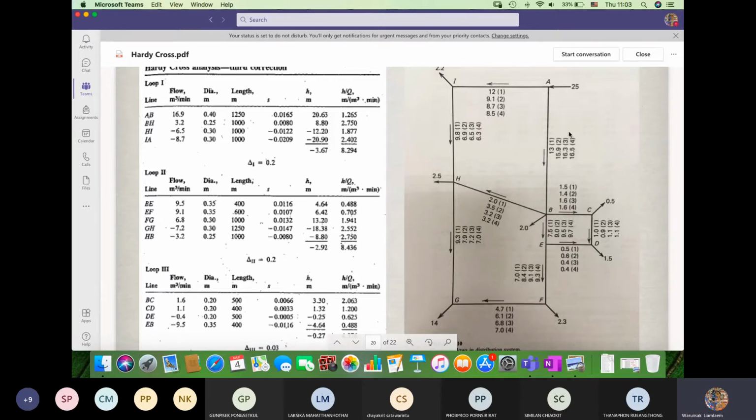Same as the other pipe, AB, the first trial, we get 13. This is actually the assumed flow. And at the end, we are getting 16.5. So it increased. This we first tried with the 2. And finally, it comes up with 3.2. So after 4 trials, we pick up the updated flow rates after 4 trials for further use.